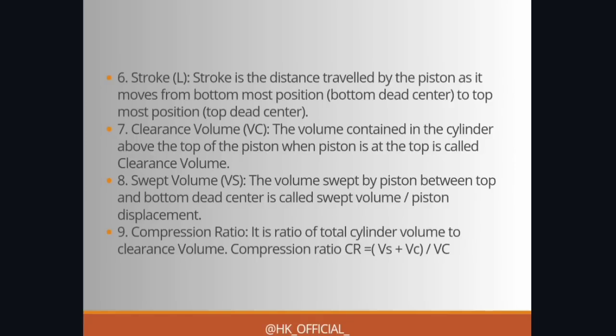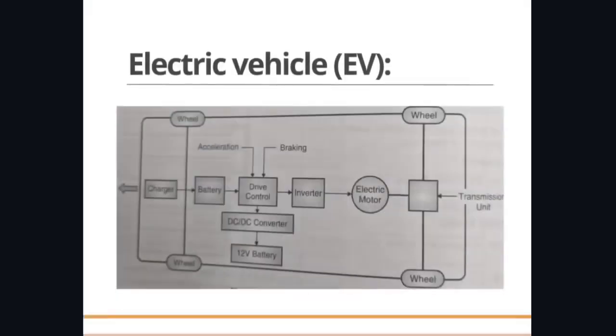Okay, now this is about volume. So this is swept volume. Then compression ratio is there. It is the ratio of total cylinder volume to clearance volume. So you can write in mathematical form like Vs plus Vc upon Vc. So this was about compression ratio. These are all the specifications. Now let us go ahead.